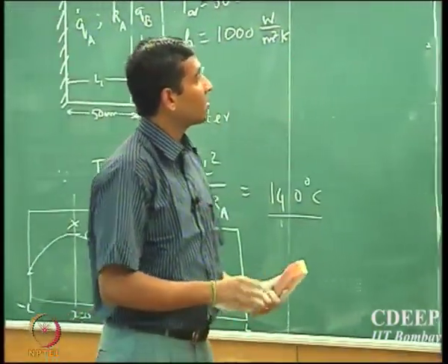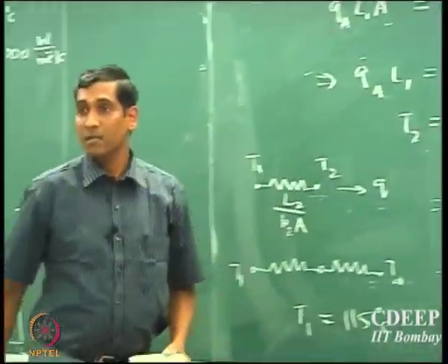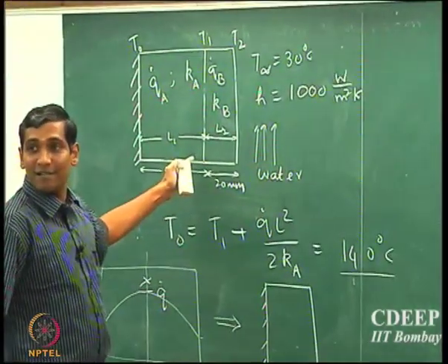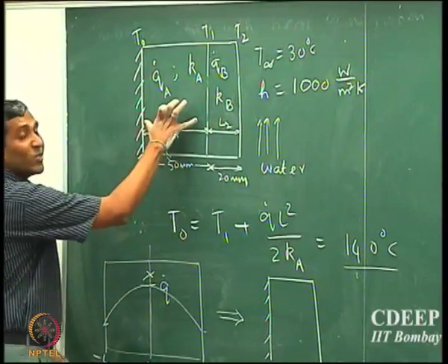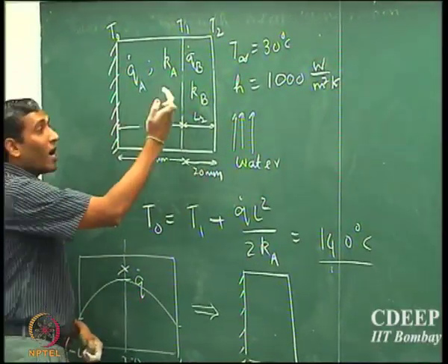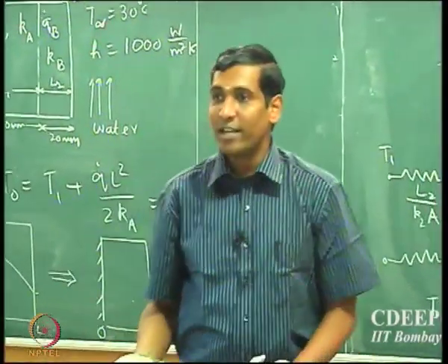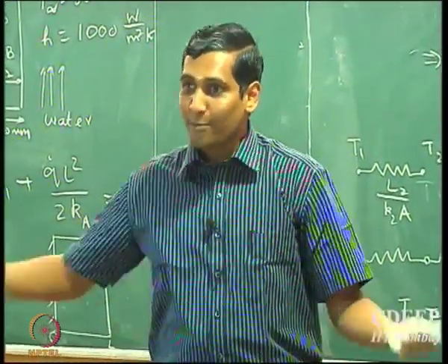Yeah, conduction is included in Q B. This is the balance at the interface. So all that is generated... note that the conduction is happening inside the slab, right? So at the boundary, what comes out of the boundary is the total amount of heat that is generated inside the slab. Of course, it comes through conduction.